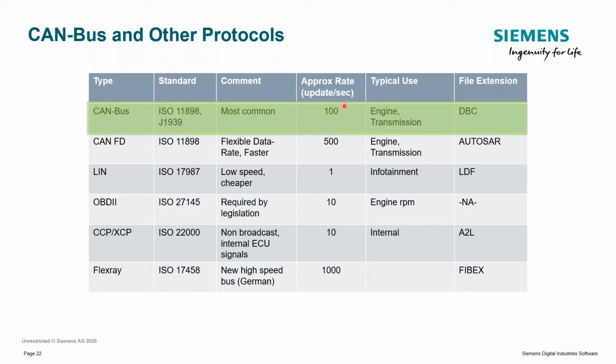About 100 updates per second on a channel you can get, maybe even more, depending on exactly how many channels you have coming through on the CAN bus. It's fairly fast, not as fast, obviously, as 100,000 samples per second, like a SCADAS can do. But the need came, more and more electronic sensors embedded inside products, and so there's a higher throughput rate needed to communicate between these different electronic control units. And CAN bus was reaching its throughput limit. No more messages could be crowded in.